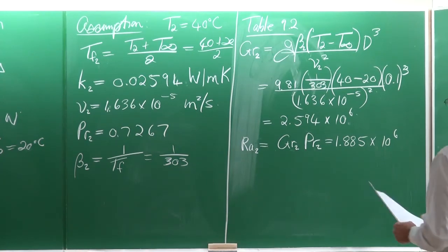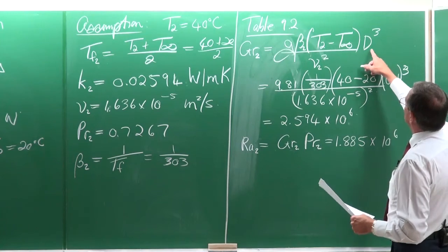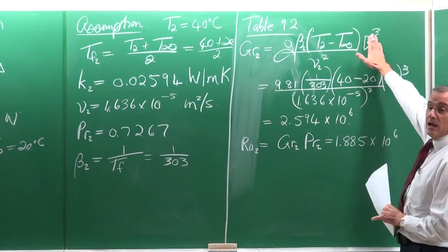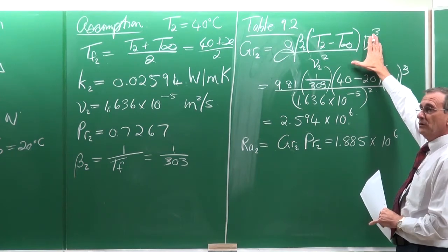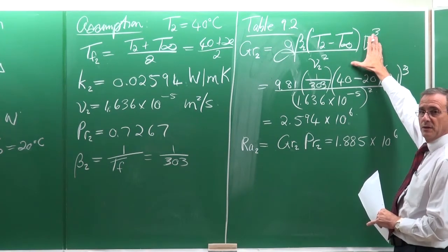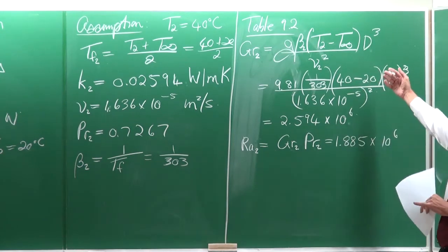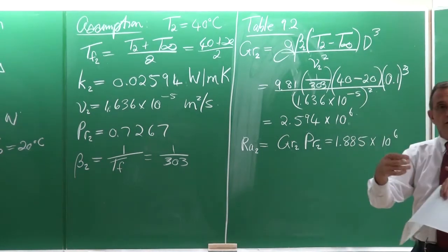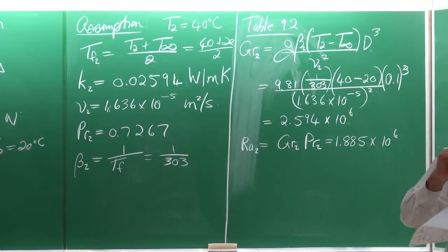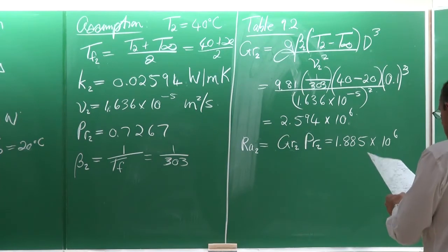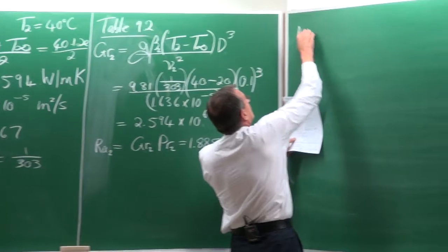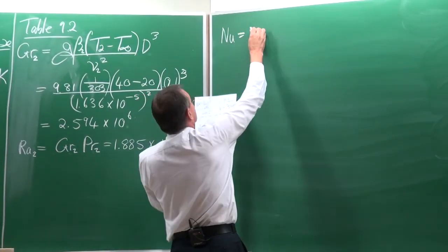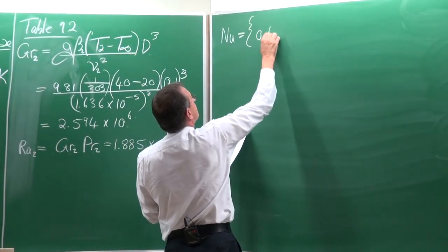That is actually quite a very important dimension. It can be an L there. But how do I know if I should use the diameter or which diameter I should use or the length? You have to go and look at the formula, the information that has been given, and you'll see for a tube it is the outer diameter D that should be used as the characteristic length. So from table 9.1 we can get the Nusselt number equation that we have also used previously.